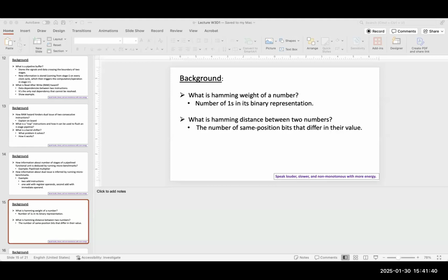I think it is already answered. They are deducing here that there are two ALUs present by the fact that you can do two arithmetic instructions at the same time. I haven't copied everything, but you can do the two ALU operations at the same time only if one of them is immediate. Which tells us something about the register file.